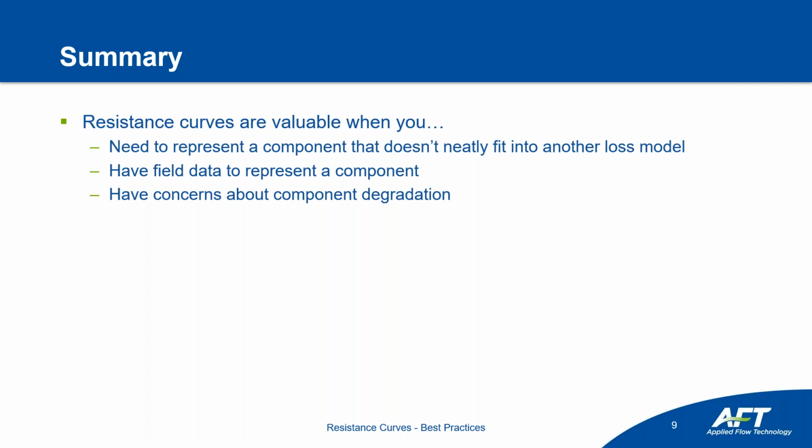So again, as I mentioned, it's a relatively brief webinar. Hopefully you have some opportunities to implement resistance curves into your own systems, but let's review. Resistance curves are valuable when you, for example, need to represent a component that doesn't neatly fit into another loss model. Common cases are heat exchangers or cases where you may not have datasheet information. If you have field data to represent a component, generally the closer you can get to actual field measured data, the more representative your model will be.